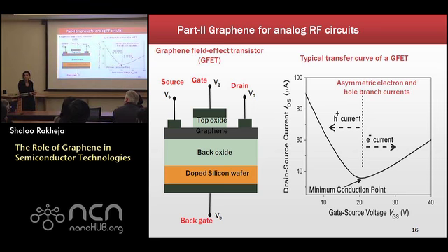So my question is that even if the capacitance is smaller, the resistance in the copper should be smaller because you have thickness. You can increase the thickness and the resistance will go lower. But in the graphene, you just have 2D. So RC, I didn't guess that. That was the point. The point is that for RC or for delay performance, graphene does not really compare very well against copper interconnects. And we were targeting very short local interconnects. And even for short local interconnects, the conclusion remained pretty much unchanged.